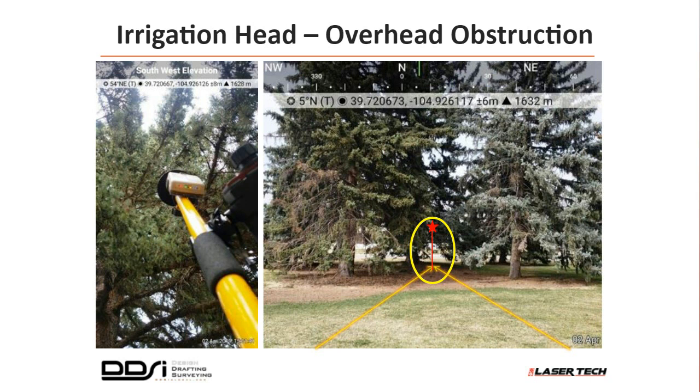We could have tried to stand in that spot, maybe average 30 to 40 points, and ideally hope for the best. But why chance it? By using the range routine, we could step out into the clearing, allowing us to gain a fixed GNSS position to get sub-inch control point accuracy to then perform the laser offset routine. A single field crew member was able to solve the problem without having to stop, reassess, and potentially ask for help to acquire the single point feature.